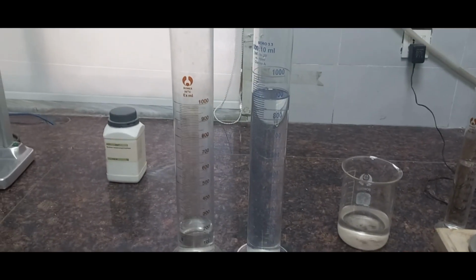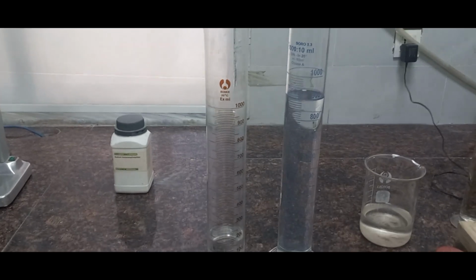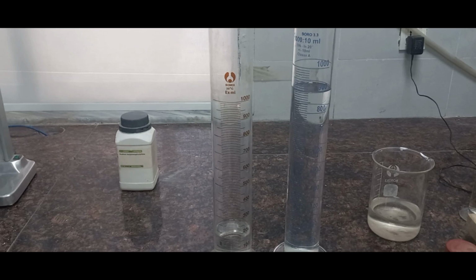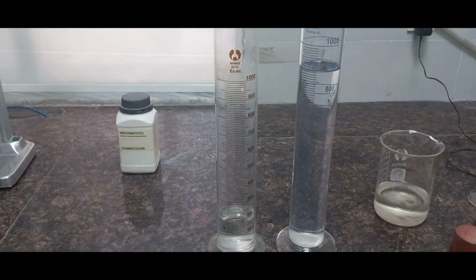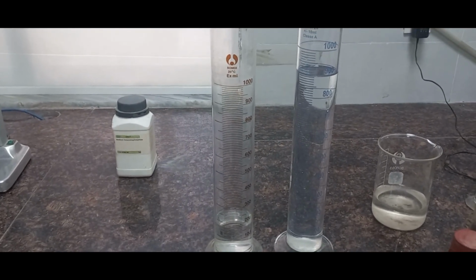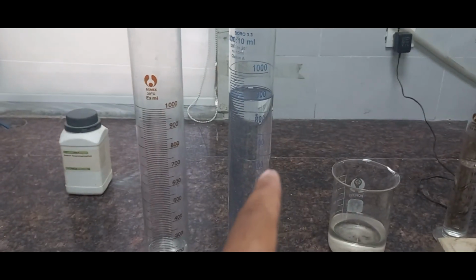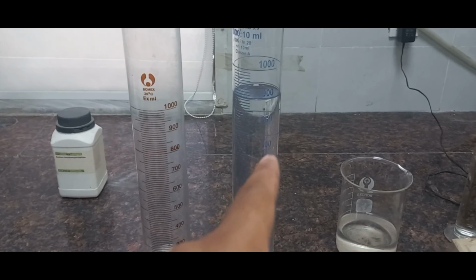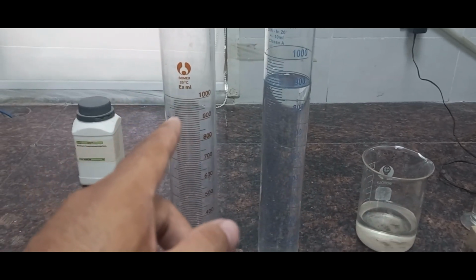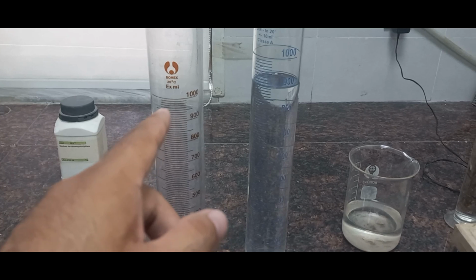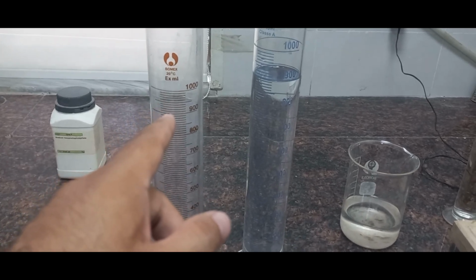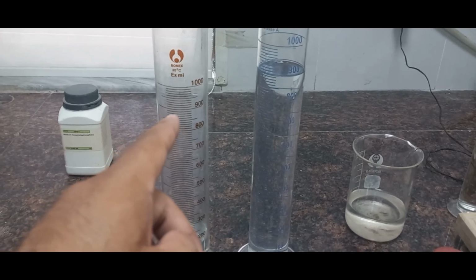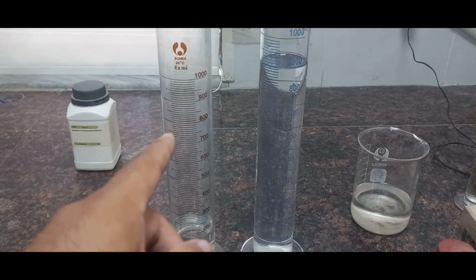After that, we have to prepare our soil specimen cylinder and reference solution cylinder for hydrometer readings. For that purpose, there is a cylinder filled with plain water and the other cylinder filled with distilled or plain water mixed with 5 gram per liter sodium hexametaphosphate for the hydrometer reference solution.